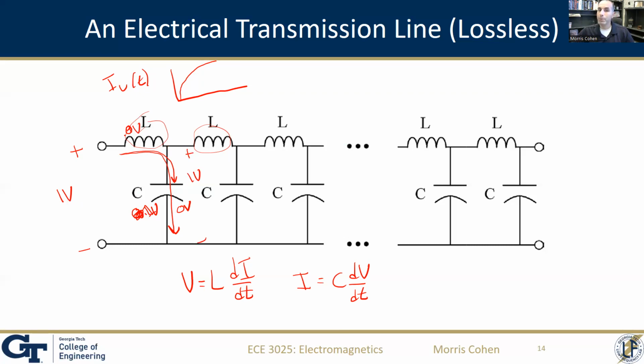That process will then repeat. Once you establish the 1 volt, 1 branch in, you're going to start to charge up a current across this inductor, which will turn into a current across this capacitor, and then the 1 volt will appear across the capacitor, and so on. This will continue over and over again.